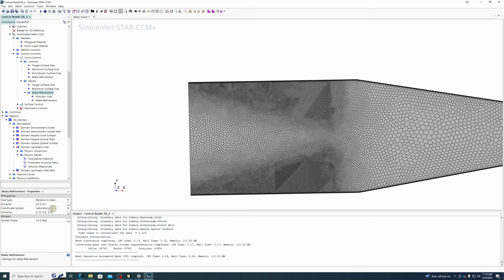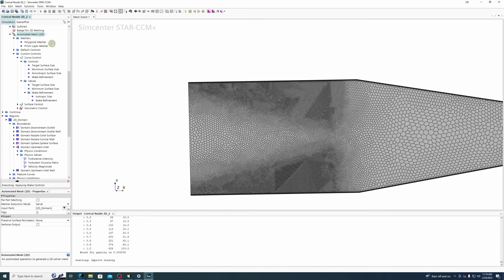Let's see here. What else? We can specify the direction. Okay. Let's go ahead and say 1 positive x, but also negative 1 y. So this triangle should extend, well, for this lower corner, it's going to extend out of our domain. For this upper corner, it's going to extend kind of into the middle here. So let's go ahead and execute this.